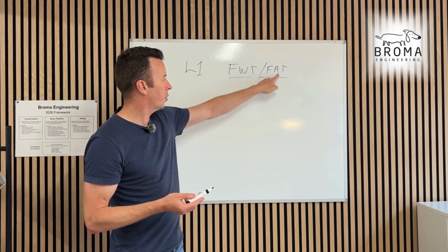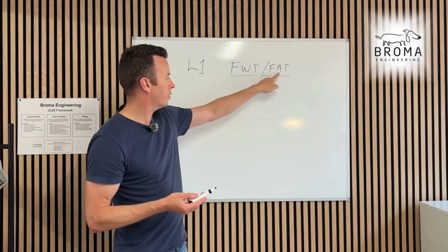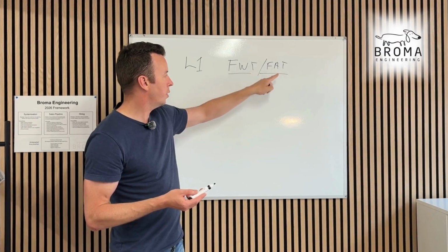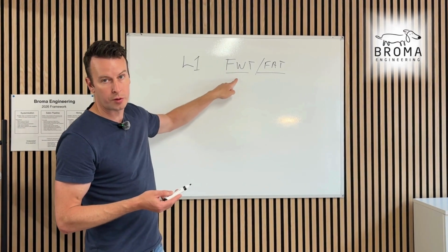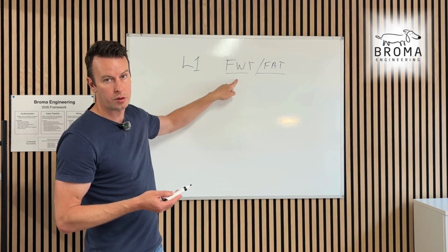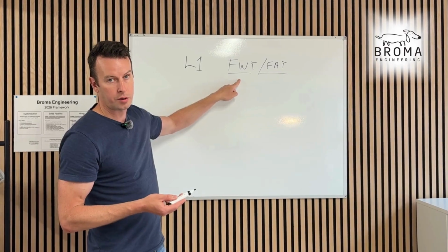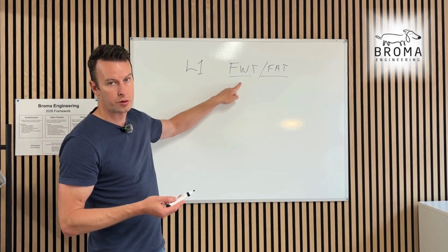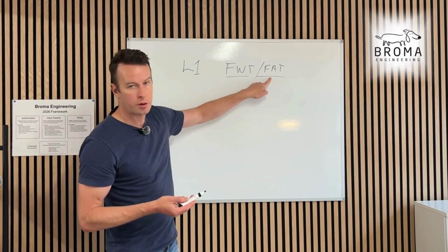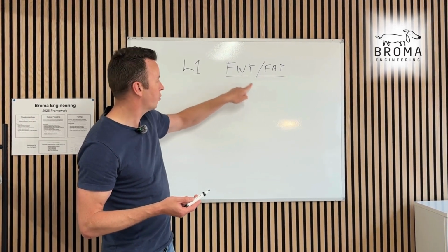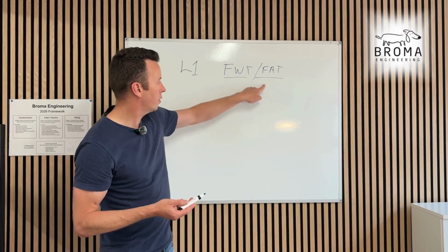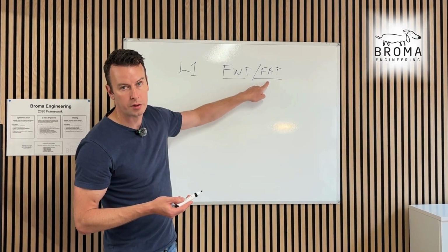But recently people are calling FWTs FATs, of acceptance. For me, factory witness was always the big one, the first of a kind, the first AHU out of the factory. Everyone comes, everyone makes sure it's right, and then the vendor does all the FATs after that. If you have 20 AHUs, number 1 is an FWT, the 19 after are FATs.